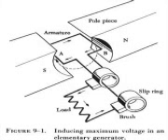To correct this condition, the brushes are set so that the plane of the coils which are shorted by the brushes is perpendicular to the distorted magnetic field, which is accomplished by moving the brushes forward in the direction of rotation. This operation is called shifting the brushes to the neutral plane, or plane of commutation.